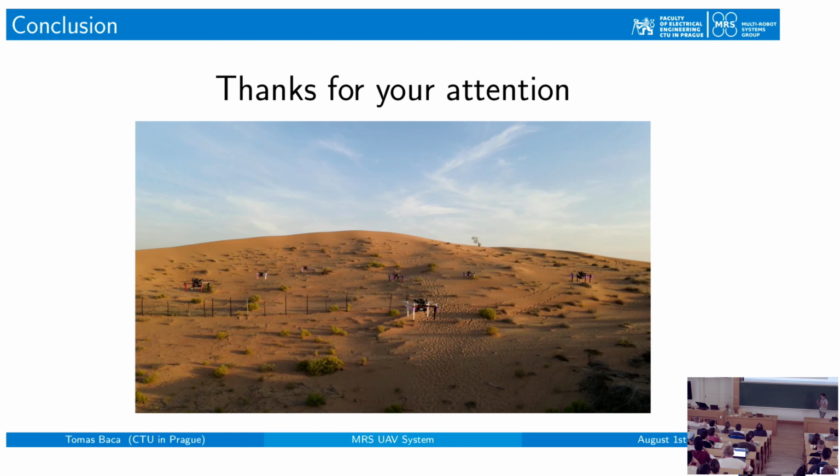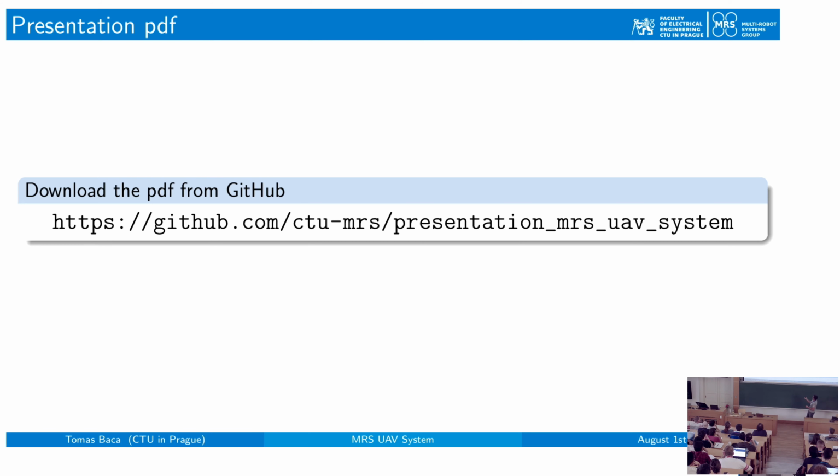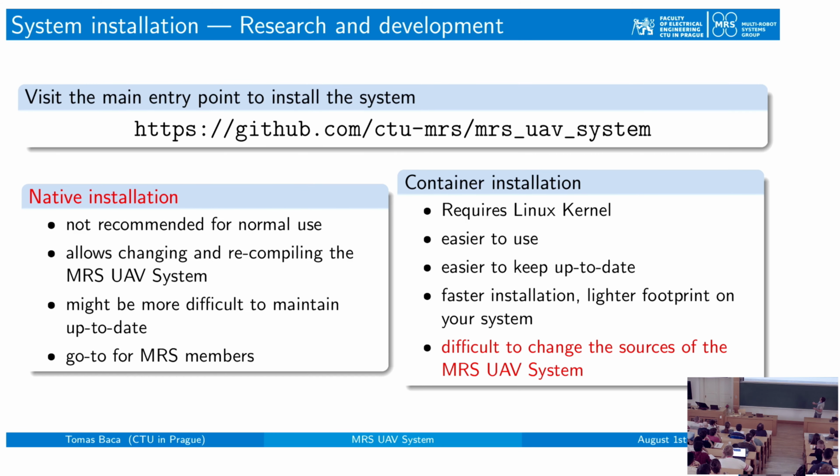So regarding the MRS UAV system, where are we? It jumped at the end. So the MRS UAV system can be installed in 2 basic ways on your computer or on the drone. The first and traditional installation way is native installation, which I don't recommend right now. Don't do it if you don't have to.